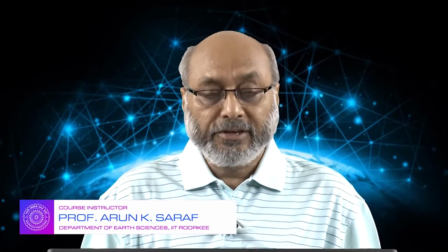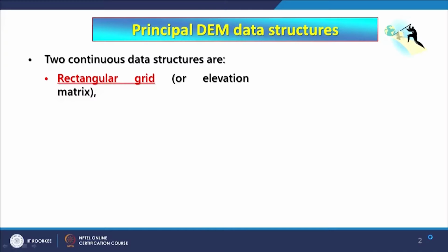Today we are going to discuss a triangulated irregular network, that is TIN data models, and we will try to compare with the raster data model because both are continuous in nature and therefore a true comparison can be made between these two data models. And in between I will also mention a little bit of comparison about vector data. So, let us first try to understand what basically TIN is.